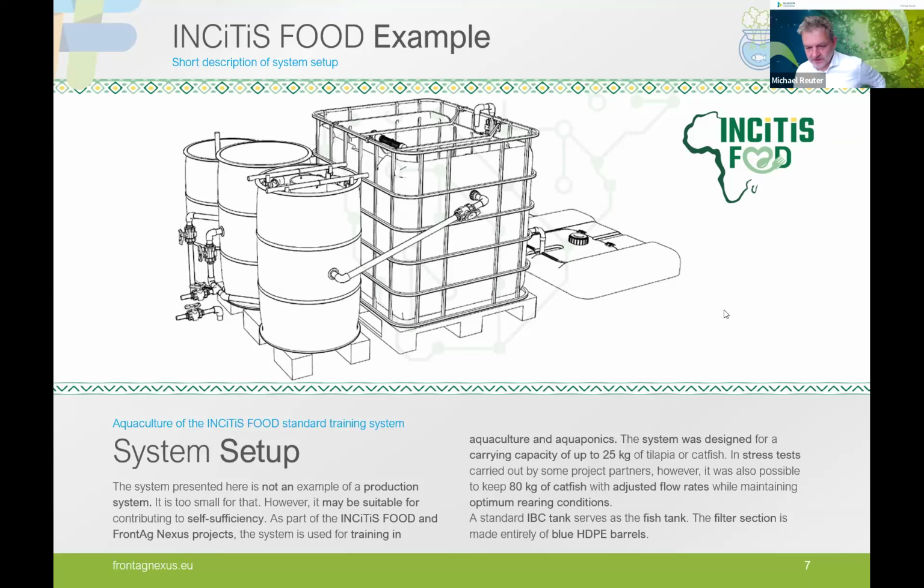The system is designed to allow a carrying capacity of 25 kilograms of fish, either tilapia or catfish. But we also had some partners who did stress tests with this system up to 80 kilograms of catfish per cubic meter of water with adjusted flow rates, obviously. But this showed that the system can handle quite more than 25 kilograms, but we will stick to that with all our examples because it's the way we usually want this system to be operated.